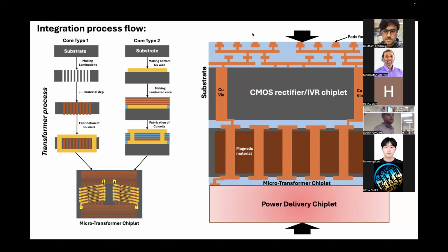Okay, also one more thing: it really depends on the frequency. If you want to operate this at say 100 megahertz, these laminations are essentially going to be like 200 nanometers thick. So you have to end up using some deposition process, some PVD process. If there's some spun-on dielectric, it doesn't have to be 200 nanometers, it can be tens of microns.